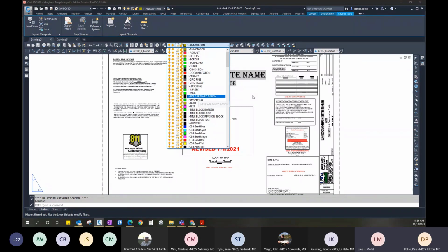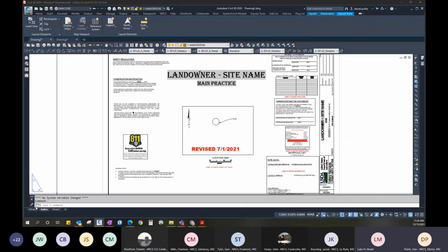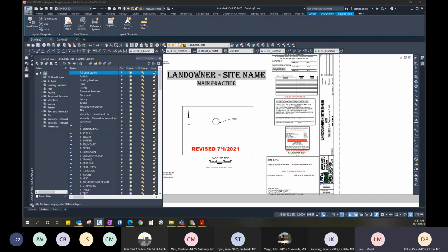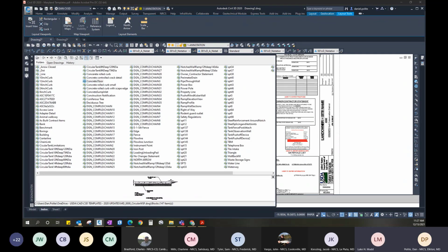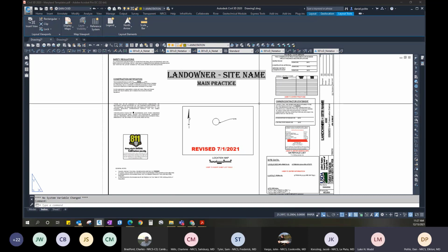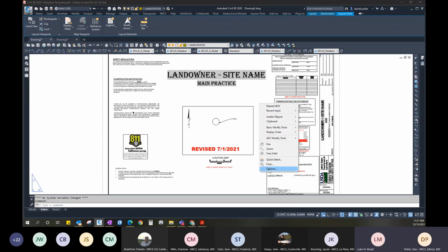But basically what happens is you do all your electronic red lines and then turn off all your layers. And then all you're doing is XREFing your signed PDF into this drawing, pasting it, and that's the only time you do plot paper space last, because basically you want your actual PDF underneath all of your as-built statements.